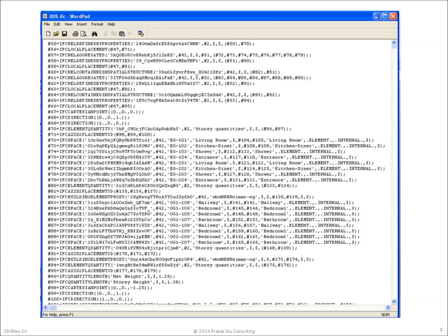In this video, we're going to talk a little bit about the envelope, the formats in which COBie is delivered. When someone talks about an IFC file, what they're generally talking about is a file of a format that looks like what's shown here. This is an ISO 10303 or STEP physical file model. Obviously, this is not a thing that a human is supposed to read. This is a file whose intention is direct system-to-system information exchange. But since a lot of the information that's contained in COBie needs to be viewed by people, maybe this is not the best format for all of the uses of this important facility, asset, operations, and maintenance data.